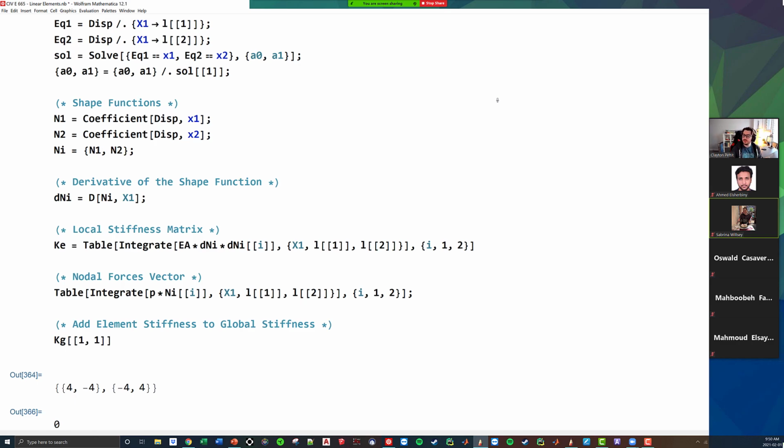So what we're going to do is take these degrees of freedom and translate them to the global scale. So I'm going to switch colors again. So we know that this corresponds to 1, 2, 3, 4, 5, 1, 2, 3, 4, and 5. Now, if I look at this element right here, we know it goes from 1 to 2. So therefore, this is the same as 1, 2, 1, 2. Does that make sense to you guys? What do you guys think in the chat? Pretty good?